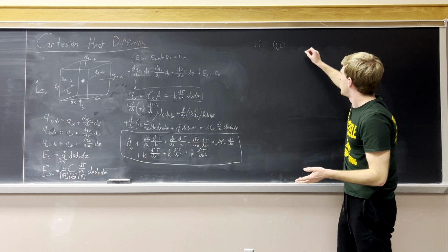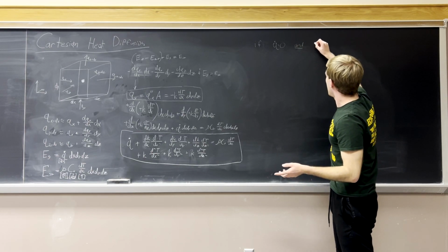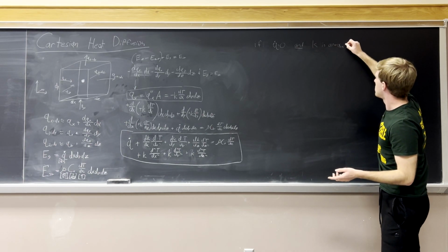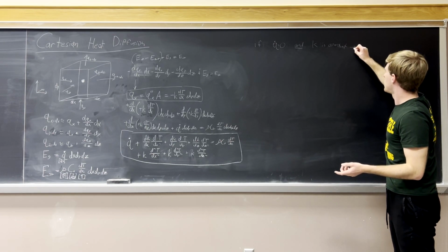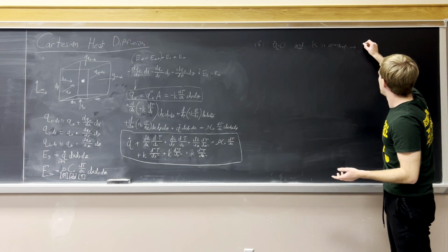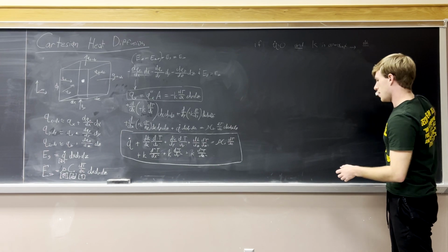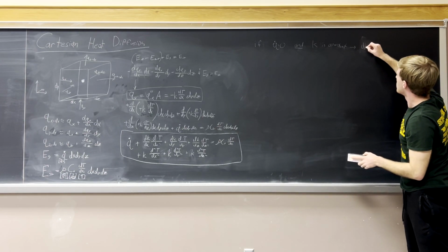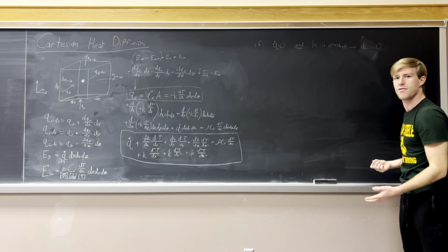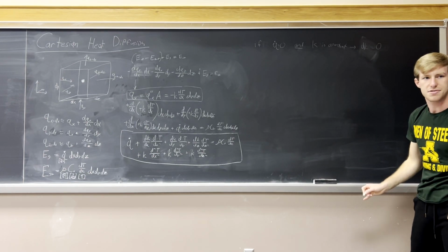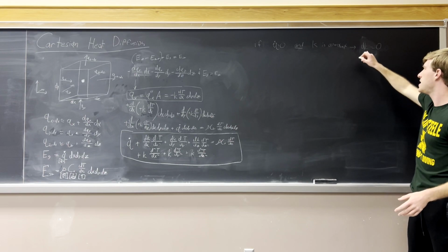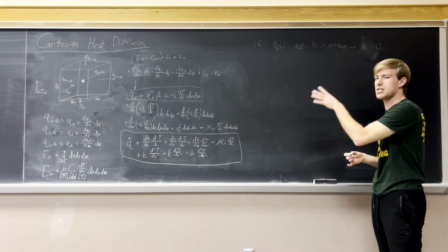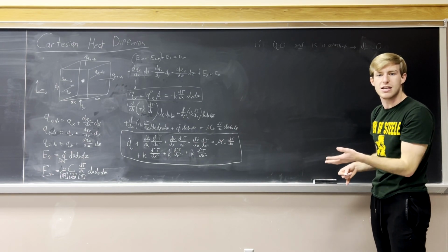The other thing we're going to do is add another assumption right here: K is constant. So what does it mean if K is constant? Well, that means that the derivative of K is equal to 0. Let's say dK is equal to 0. And you notice I didn't use the bottom of a fraction because constant implies that it's constant across all axes. So dK with respect to the x direction, the y direction, the z direction, all of it, we're assuming our material is homogeneous heat diffusivity wise.